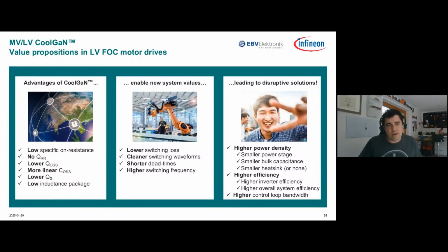We find that very often these waveforms are so free of ringing and EMI that they enable designers to increase the dV/dt quite a lot. And the inverse of dV/dt, of course, is time. So this means if you have 400 volts or 48 volts and you need to commutate that, you can do it in fewer nanoseconds and reduce your switching loss.